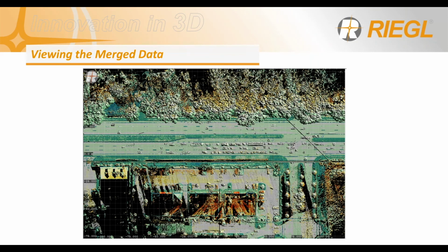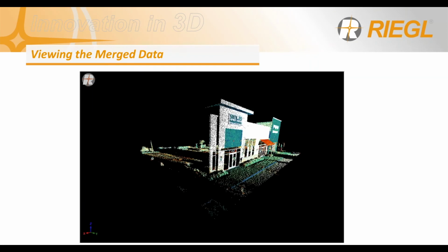these buildings here. So we had about, like I said before, about 9 scan positions set up around this building to gather those details. And as you see in the 2D viewer, they've now been merged. So taking a look even further, this is the 3D view of that same building with just the mobile scan data. As you can see, we just kind of hit the front of the building. We got a little bit behind maybe the side, maybe some points shooting through the windows, and we didn't catch almost any of that parking lot at all.